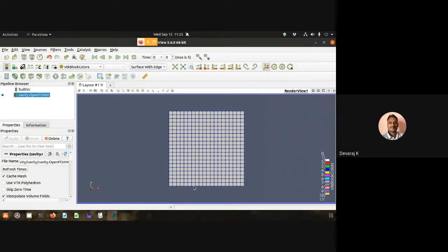Now what I want is, maybe in the Y direction, I want it to be 0.1 or 1. That means I want to have a refined mesh here or here. One of the surfaces should be refined. Maybe you might have come across some kind of boundary layer problem, where I want the mesh to be refined at one surface and coarse at the other end.